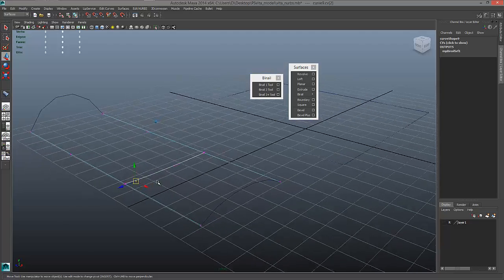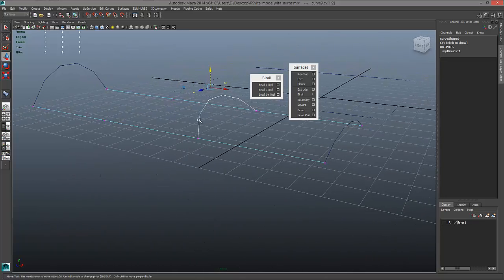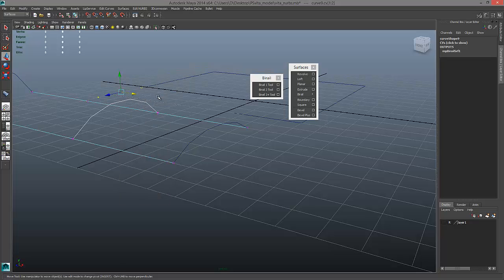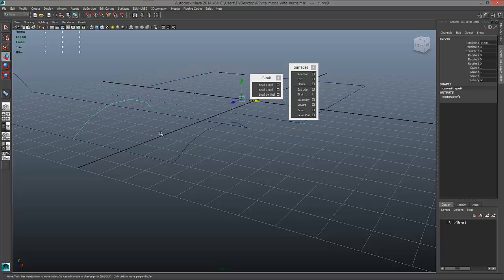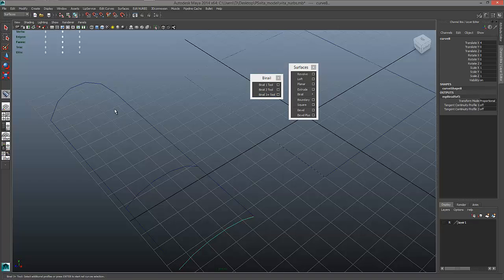And the other thing I'll have to say is that bi-rail 3 is really one of the most temperamental of the bi-rails. So let's go back here. Let's look at this. I'm going to undo this bi-rail, and it looks like this bi-rail might have failed. So I'm going to say bi-rail 3 rather, and I'm going to get 1.